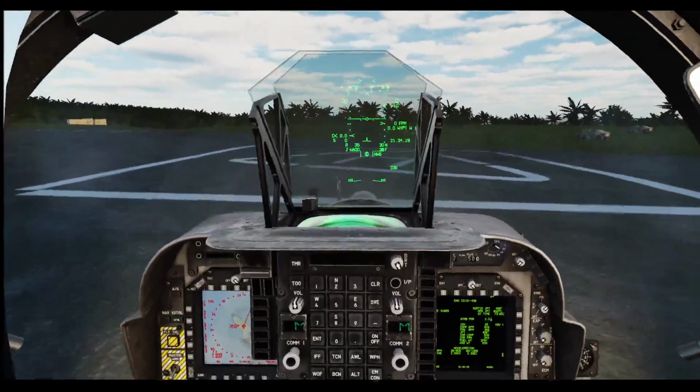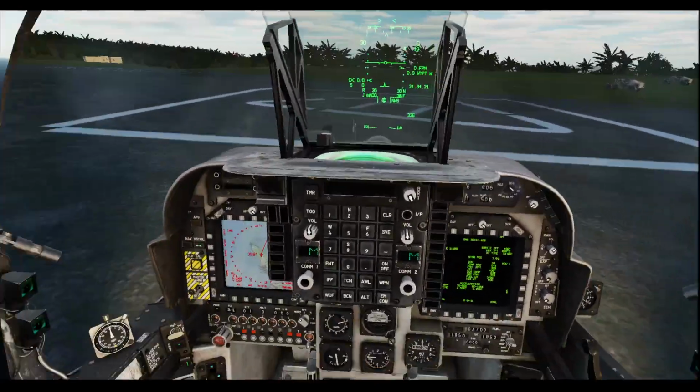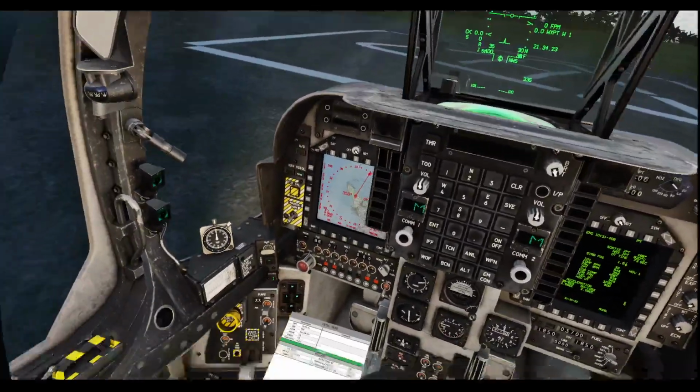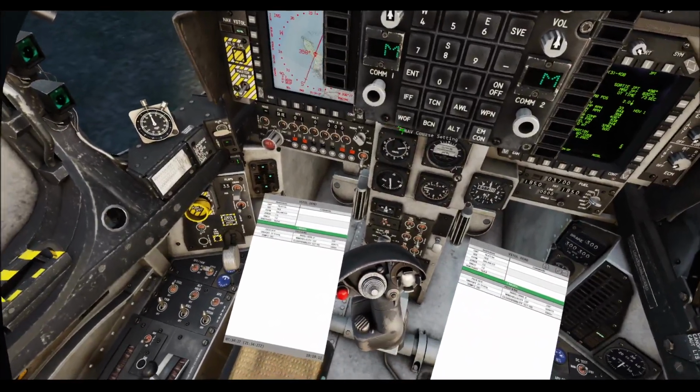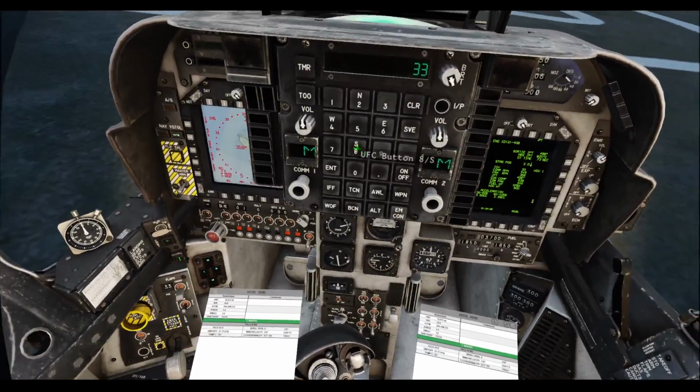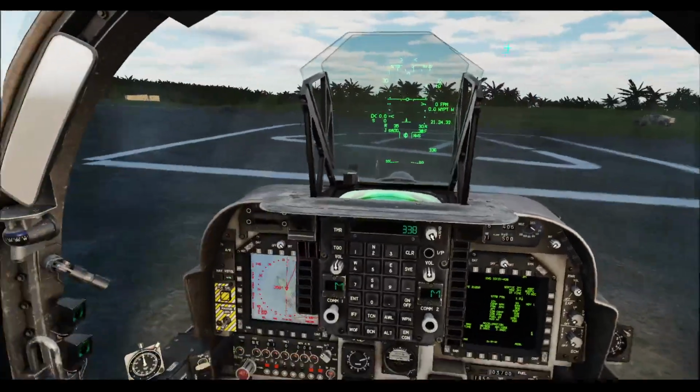I'm not going to perform a 2 or a 5 finger check. In this case, it would be 5 finger because it's water on, just for the expedience of time. And one last thing I forgot is the course line, which is imperative for accurate circuit flying.